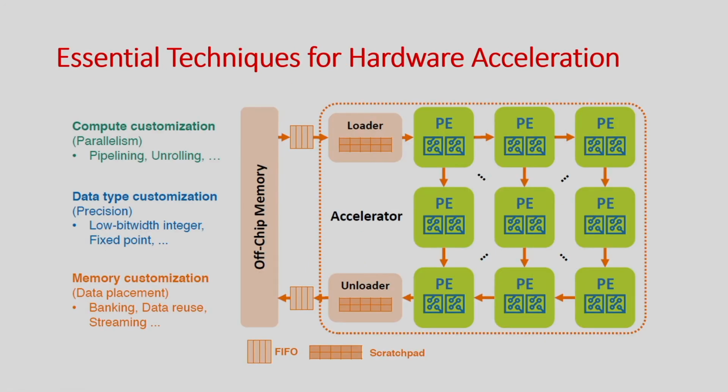So, the basic idea of efficient hardware generation, this is the architecture you want in the hardware. You have to identify what is the actual minimum computation happening, just like in matrix multiplication, basically multiply and accumulate, and you can break the whole computation into small components. You connect them in a systolic array format, so that you can propagate the data from one component to another, and then run all these PEs in parallel.